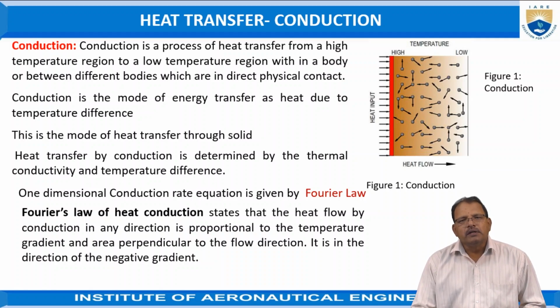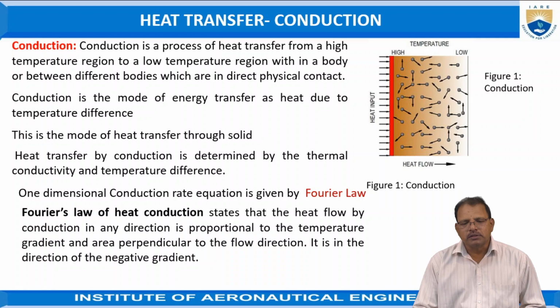Here, the heat energy flows generally from the body which has a high temperature to a body with a lower temperature. That means only when a temperature difference exists does heat energy flow through the bodies. Generally, this process takes place in solids only. The amount of heat energy transmitted between two bodies, or from one region to another region of the same body, is proportional to the thermal conductivity of the materials as well as the temperature difference that exists.